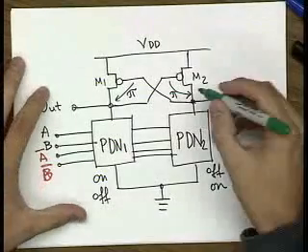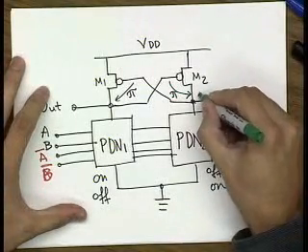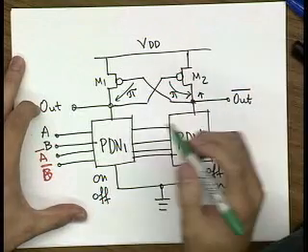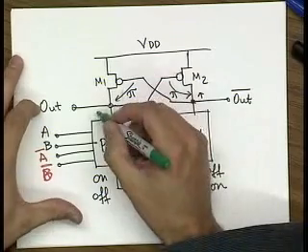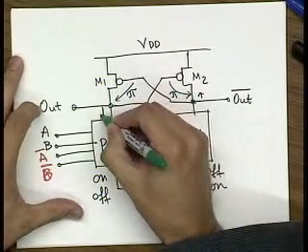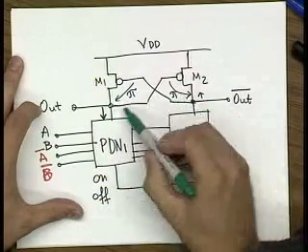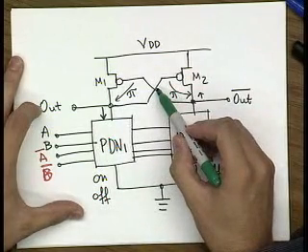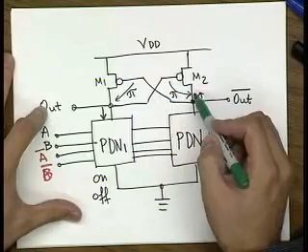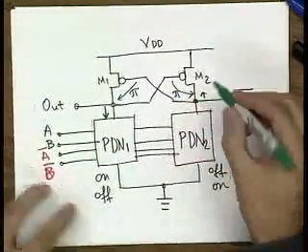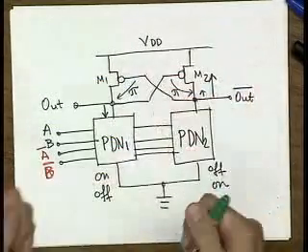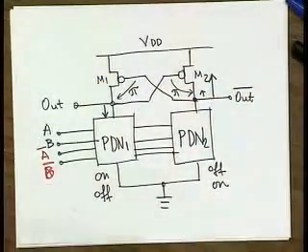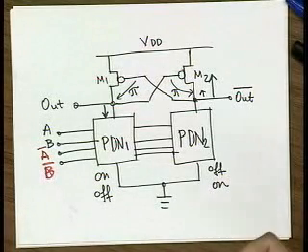What this means is basically if this voltage goes up a little bit, then due to the phase shift, this voltage is going to go down, but since this transistor is a gain stage, you have a larger amplitude. Now, that signal goes back to the gate of this guy, and it inverts again with even more gain. So you started with a small signal change over here. When you go around the loop, you end up with an even bigger change. And this feeds each other and establishes complementary levels.